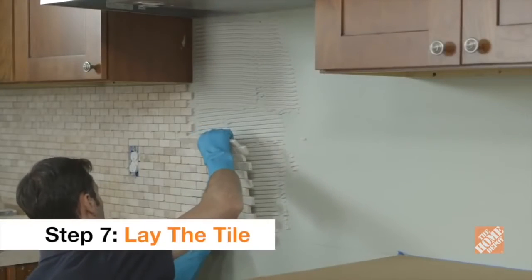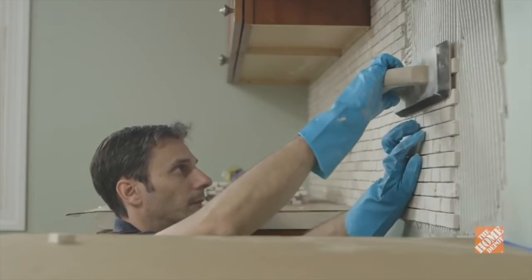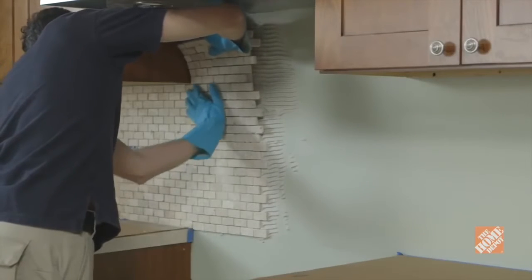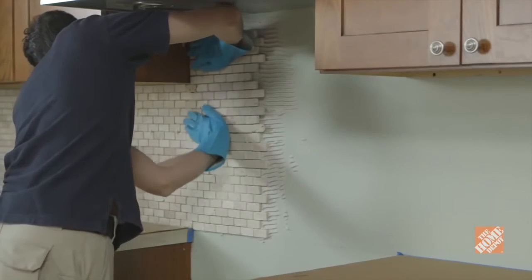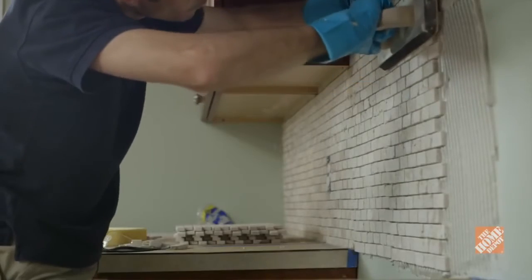Place the mosaic sheets along the wall. Add tile spacers if you need to keep the tile pieces lined up. Follow the lines that you made when the tiles were dry fit to the wall. Slightly rock the sheet up and down perpendicular to the trowel lines to collapse the ridges and help the tiles settle into place. Flatten the tile with a grout float if necessary.